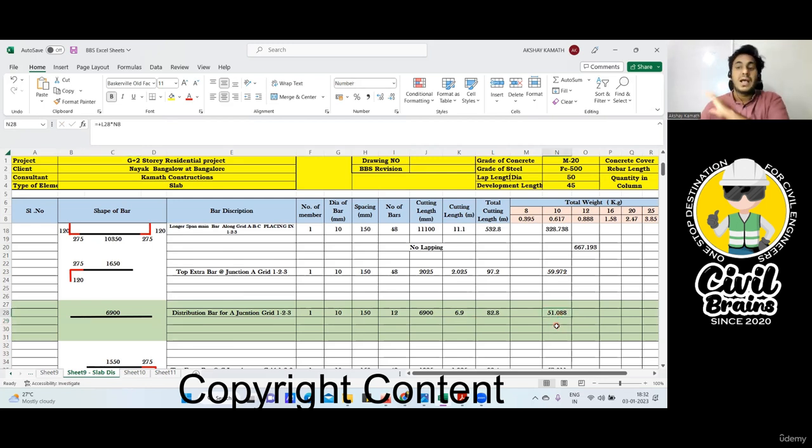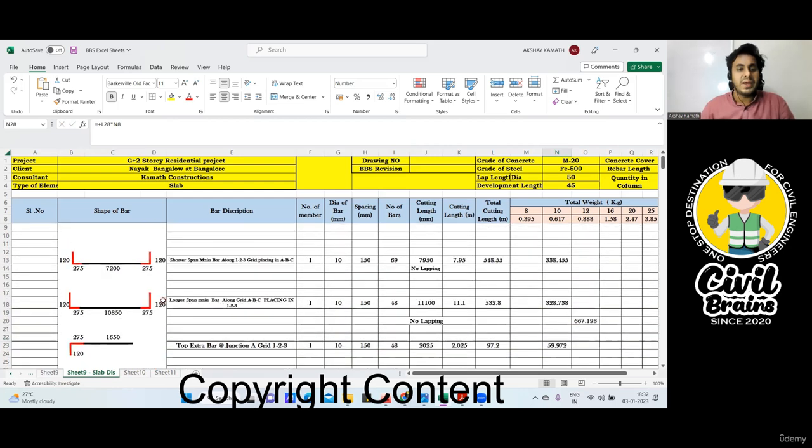If you understand this, after this, whatever calculation is the same thing. Wherever the top left, top right has come, this length only I need to take. Divide this by spacing, you'll get the number of bar of the distribution steel. Simple. Got it, no? That's it. Finish. I think with this understanding, I'll go forward one by one. Okay, for one I did.